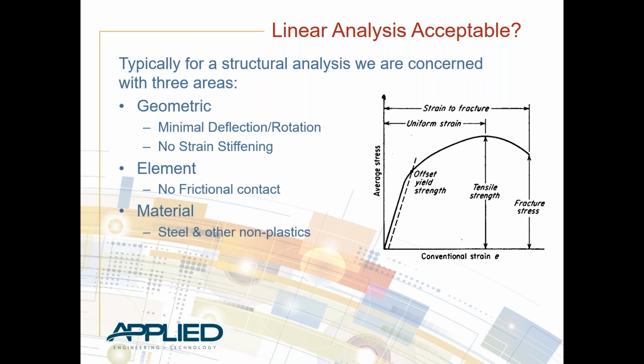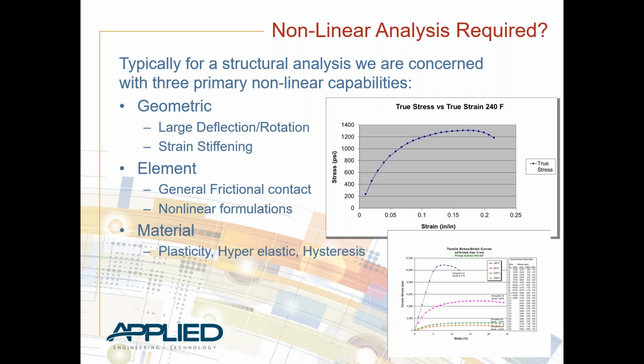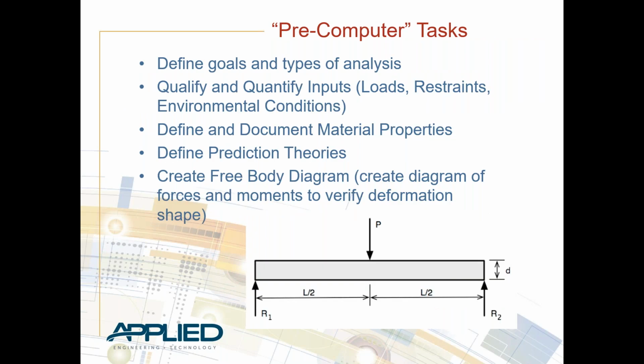In that case, if we do have some strain stiffening, things like that, where our stress strain curve has no real linear portion, or at that point temperatures are involved, things like that, we need to get into a nonlinear analysis.